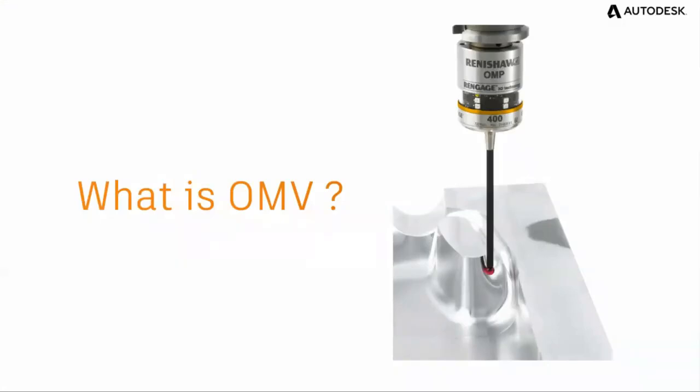So you have to first confirm whether the OMV application is installed on that machine or not, because the touch probe is usually attached to the machine for the center finding process. In most machines, the manufacturer decided to include this probe to find the center, but it's not exactly that if you supply this OMV PowerInspect software, it will work along with that touch probe. So the machine builder has to provide another option, which is a cost option, so that the software is incorporated with that machine. Okay, so what is OMV?